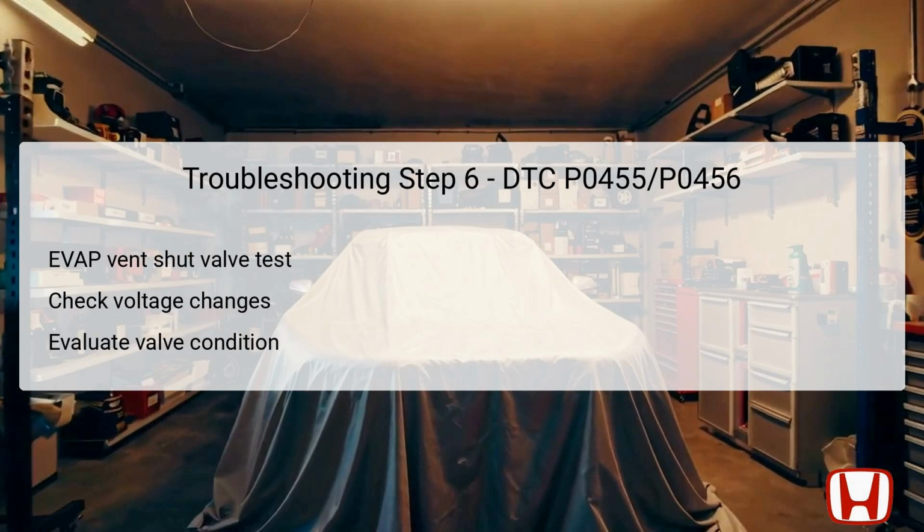At this stage, the focus shifts to the EVAP canister vent shut valve operation. First, navigate through the HDS to select the EVAP test function to turn the vent shut valve off. You must disconnect the vent hose from the valve port and then apply vacuum to that hose while still monitoring the FTP sensor. The objective is to ensure that the FTP reading again indicates 1.90 volts. Achieving this condition allows for subsequent monitoring of the sensor voltage for any increase following the vacuum application.